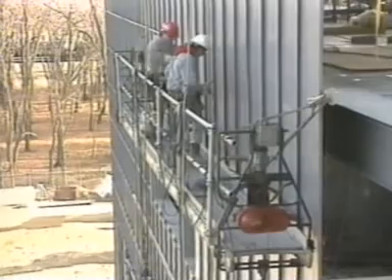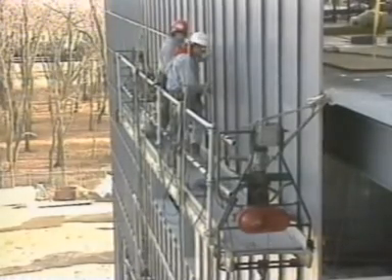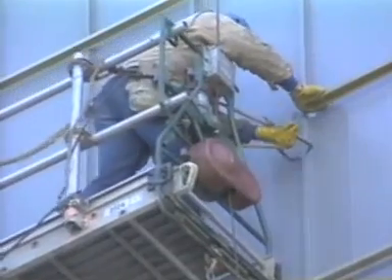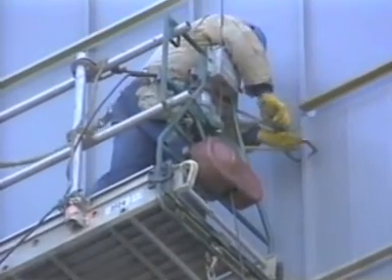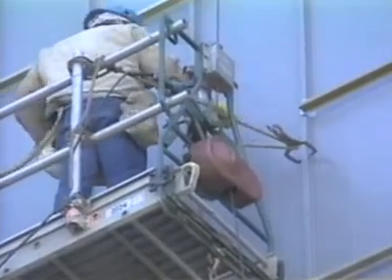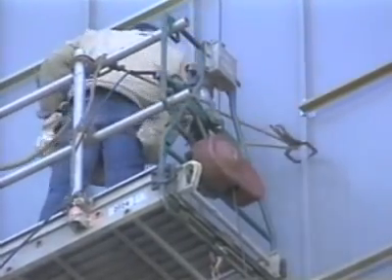Suspended scaffolds provide a work platform suspended by ropes or wires. They can be attached to a structural member, as in the case of the scaffold used by the bridge painters, or to a fixed outrigger on the roof of a tall building. These fixed outrigger beams must be at least 15 feet long and should not extend more than 6 feet beyond the bearing point. Because suspension scaffolds can swing and move in the wind, it's essential that the platform be secured at both ends by horizontal lines attached to the building or structure.